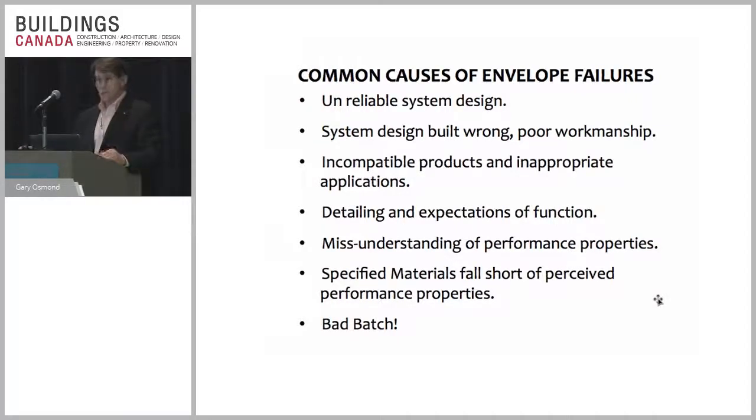We have a lot of terrific materials out there. They all function incredibly, but unless they're installed correctly, they're not going to work. And the performance properties, it's really looking at board insulation, for example, a great insulation, but it has a permeance rating. Is it the one we want? Are we going to be taping joints? Is that really what you want to do? So it's understanding the redundancy of different building materials throughout the assembly, and are they causing a problem or are they helping us along?